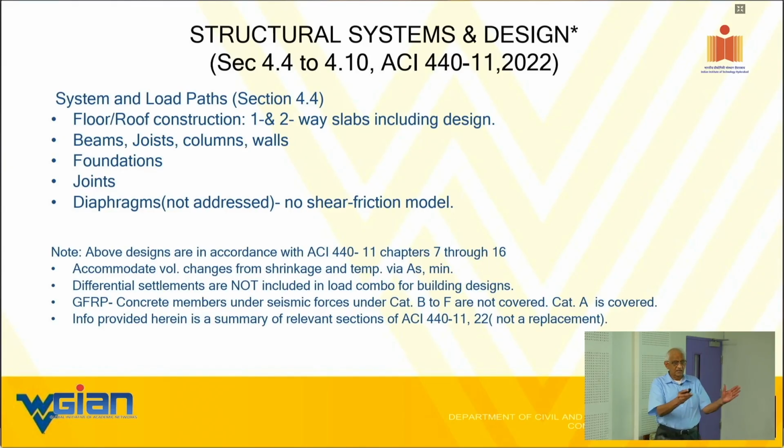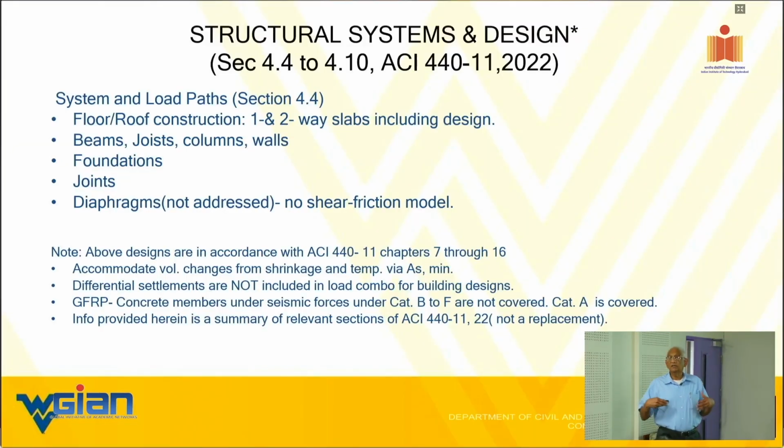I may have 3 beams like this. If they are independent, the response is one thing, but if they are connected with a perpendicular beam, the response is different. So that is what is called a diaphragm. That's one. I mean, we're talking about shear diaphragms for the walls, for example. The concept is the same. The structural function is the same, but that's a beam element, this is a slab element. That's the difference. Do you understand what a diaphragm is now?